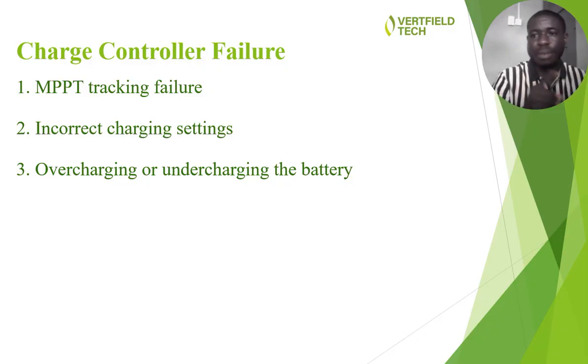Your batteries should never be connected directly to your solar panels, please. That would be a wrong thing to do. Your charge controller takes care of how the battery charges, how it discharges, and how the battery temperature rises or falls.